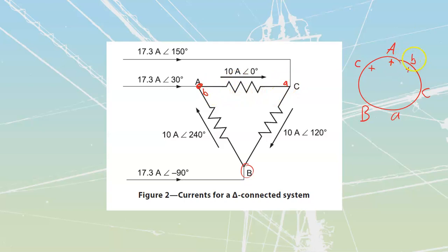And because all we're doing is making this connection on the outside, taking this one over here and connecting that one with my little b over here, we're going to have a couple of currents that are going to be adding together, but they're going to have different values of voltage, and that's just due to the way that we change the directions inside of these windings.